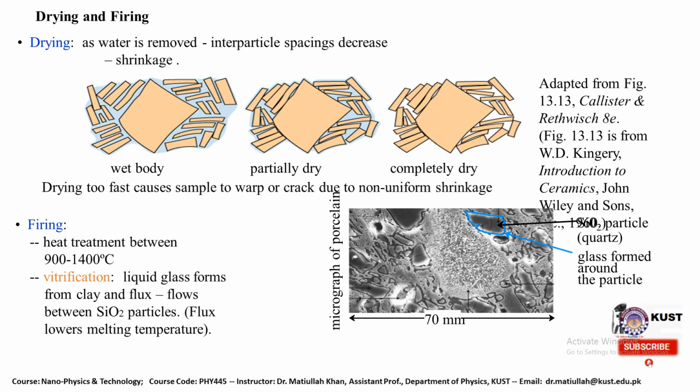The heat treatment is performed from 900 to 1400 degrees centigrade. What is the basic idea behind the firing process? It liquefies, so liquid glass forms from the clay, and flux flows between the SiO2 particles, which lowers the melting temperatures.